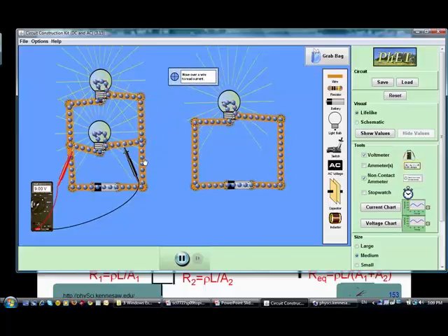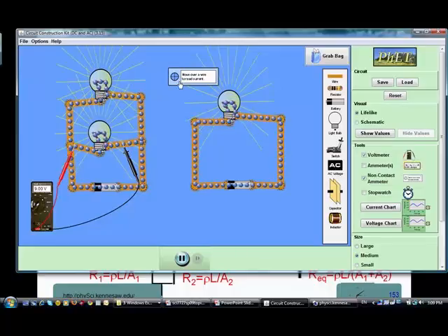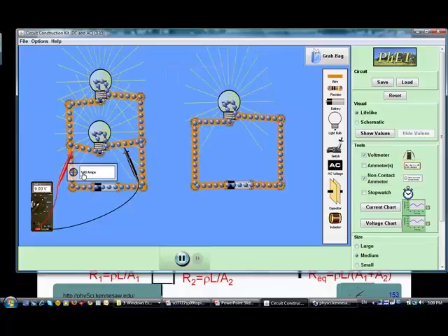So actually the charges, when they come here, they find two paths, two highways. And since the paths have identical resistance, they are going to be equally divided among them. So that the overall current is going to be divided into 0.9 and 0.9. Once they meet back here, they are going to add up again, giving us the 1.8 amps again.